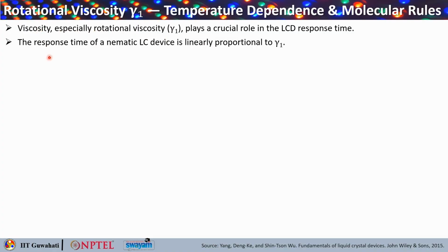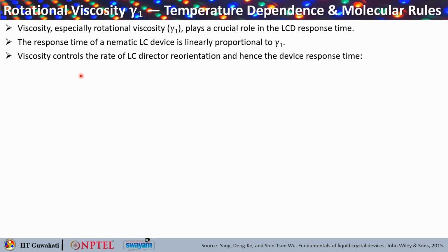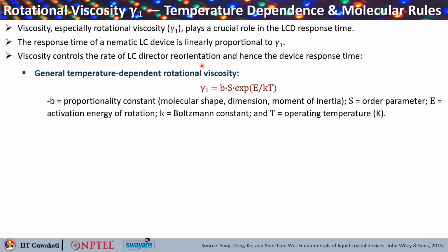Rotational viscosity has a temperature dependence and it plays a crucial role in deciding the LCD's response time. The response time of a nematic liquid crystal device is linearly proportional to the viscosity. So, the viscosity controls the rate of liquid crystal director reorientation and hence the device response time as well.